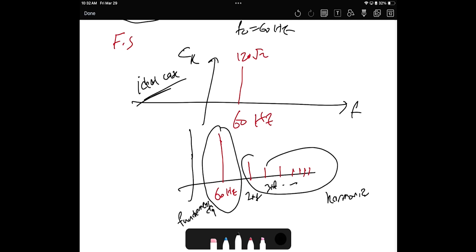These problems cause harmonics. However, there are some conditions: if the harmonics do not exceed 3%, then it can be accepted. If it exceeds 3% of the fundamental, then we need to take action. So electronics creates harmonics, something undesirable.